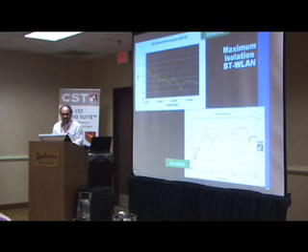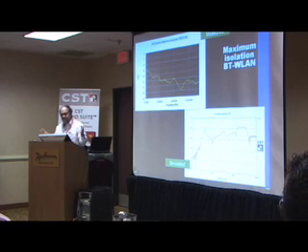Initially, when we put Bluetooth and wireless LAN on the top, we were getting very low isolation, sometimes even 10 dB. So we started swapping the antennas back and forth, and despite all that, the isolation wasn't improving. So what I did is we ran a CST simulation and tried to see if by swapping antennas within the CST simulation we could get better. And there also the maximum we were getting was 18 dB. So this indicates that we shouldn't even put Bluetooth very close to wireless LAN anywhere on the top if at all you want WiMAX to work.